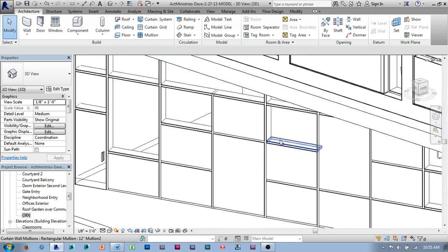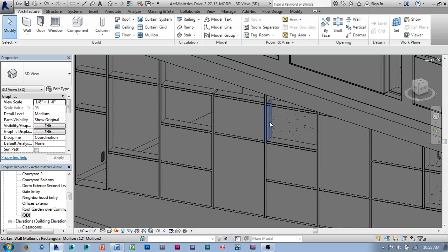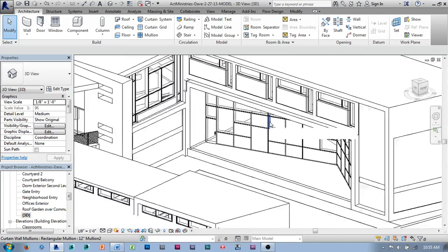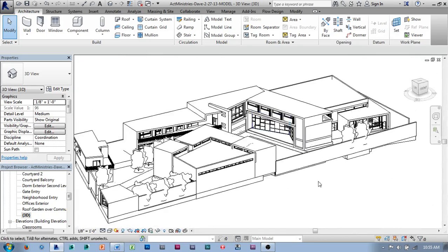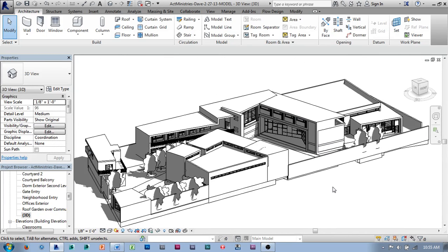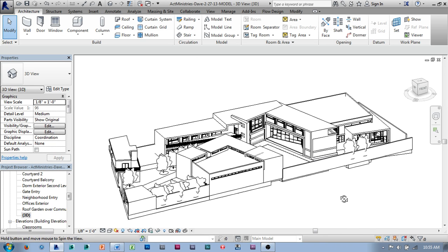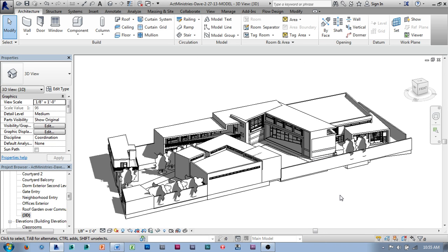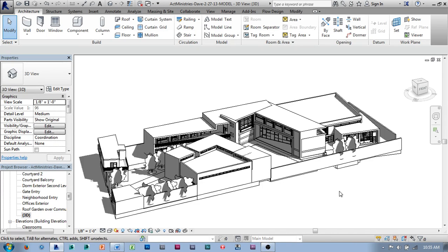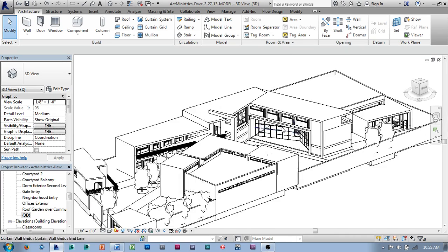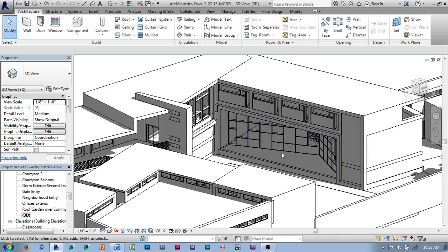For instance, if I zoom in and look at these mullions, right now they're a fairly small mullion, and I know that our Rep 2, which is an FDM extrusion printer, once you get below, let's say, a 1/16 of an inch by a 1/16 of an inch, something along those lines, the reliability of that print is going to be pretty shaky. That's usually about the cutoff point. So I know for this kind of detail work, probably things like that are going to get hidden.